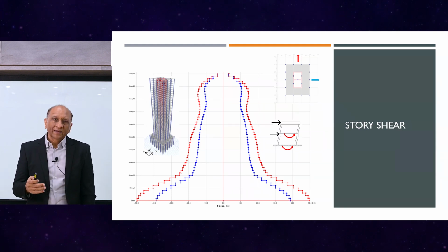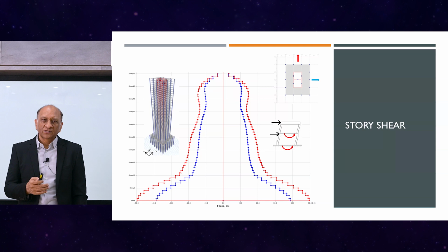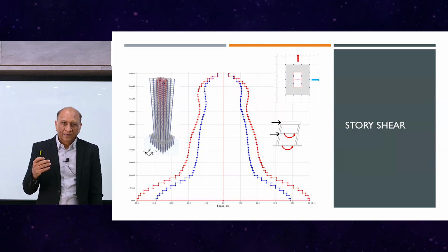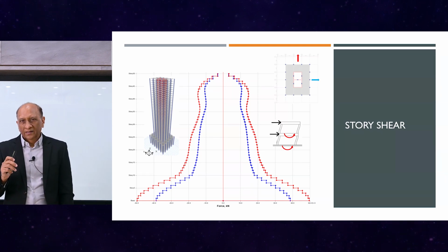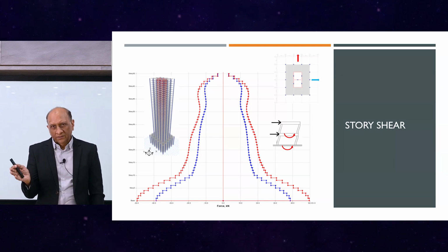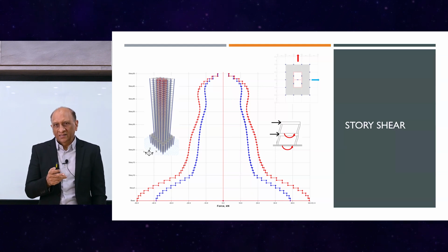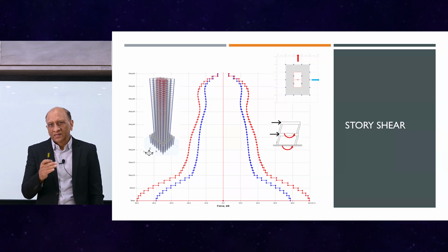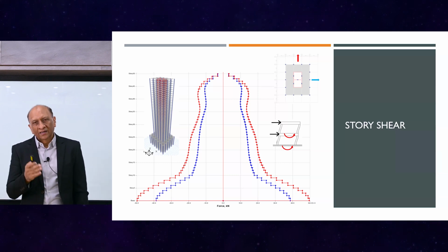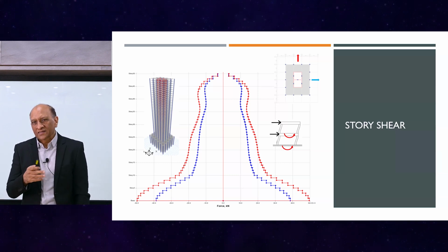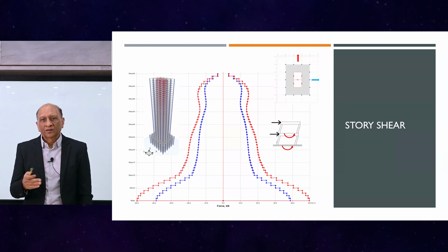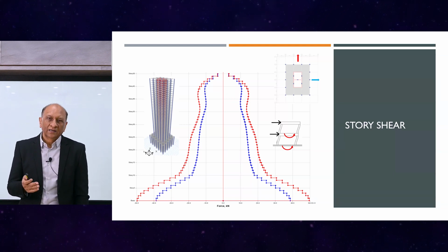Now let's go back and include these reduced stiffness in these models according to the code. Now, you can see that we are going to incorporate the green line in the analysis, which is the reduced stiffness, and the slope will increase. So we will have the green line to represent that reduced stiffness, matching more closely with the yield level stiffness.